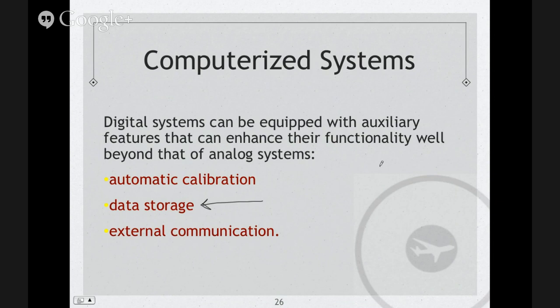So now you get another plane or another part of the same inspection, and all you're going to do is go into that setting and press recall, and it's going to bring all that back up into your equipment. Your machine is going to be calibrated again as you did last time, and you're not going to have to do it. So you can store multiple calibrations, and it's a lot faster doing it this way than having to calibrate every time for the same inspection. And external communication.